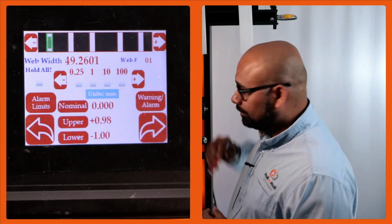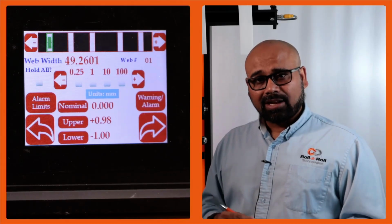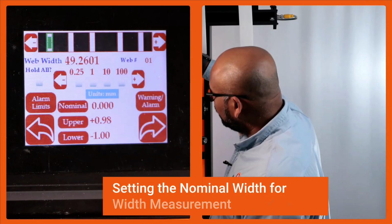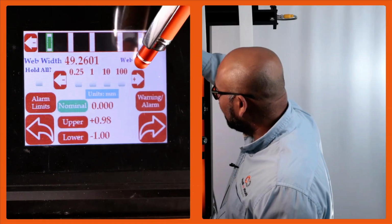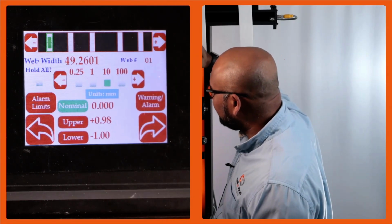Then, like I mentioned, for each web, we can set a nominal width, upper limit, and lower limit. Right now, I'm going to show you how we can set those things. In order to set the nominal width, we're going to press that nominal width icon, and then we're going to choose how much increment we want to make.